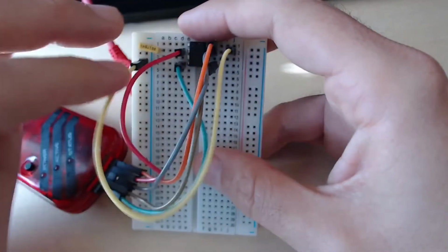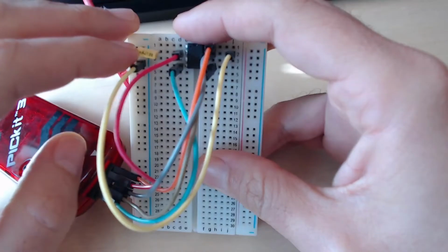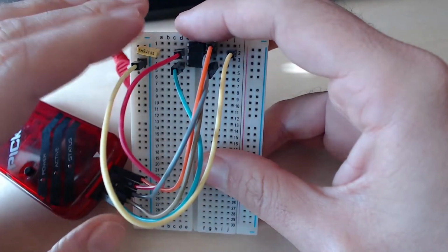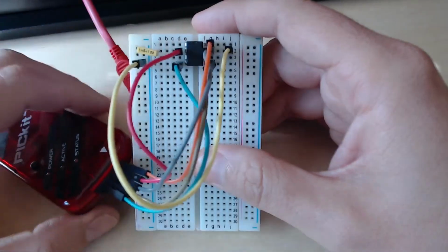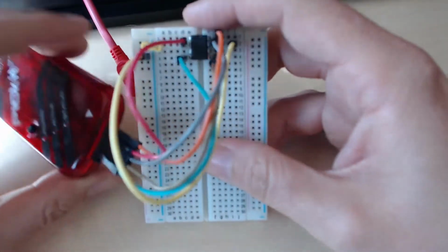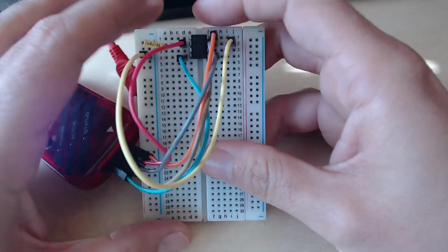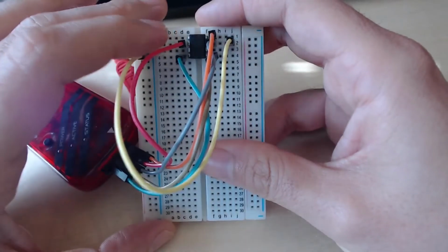And another thing is our good old bypass cap. You don't need a huge one. If you put something like 10 microfarads, it might give you problems, because your USB circuitry or the PICKIT, especially if you are powering the circuit through the PICKIT3, might think that there is a power short while the capacitor is charging. So just put something small there.